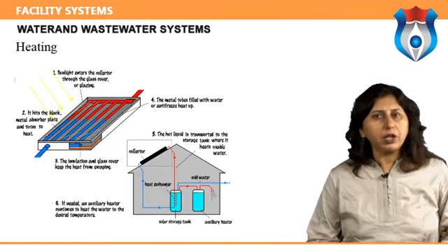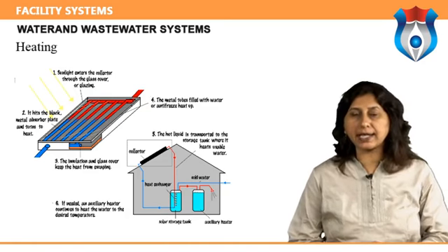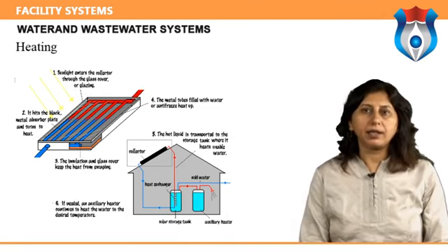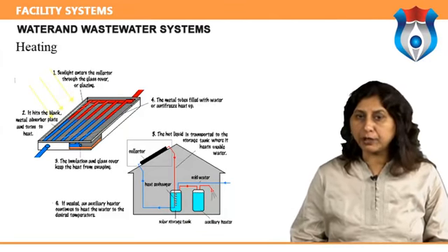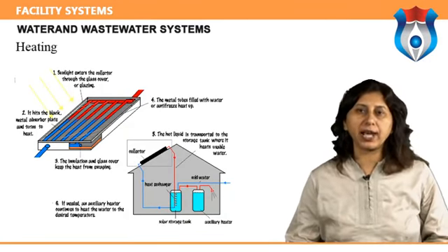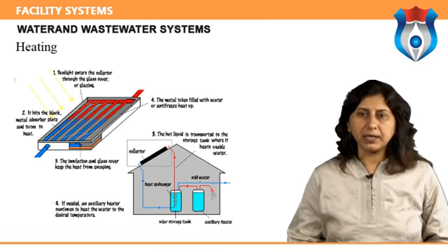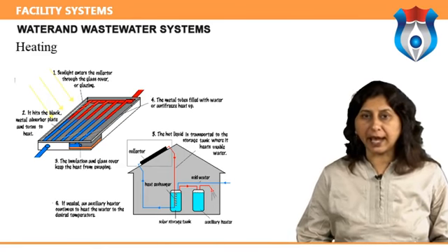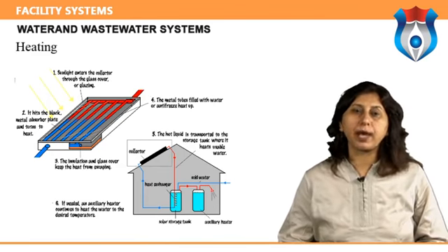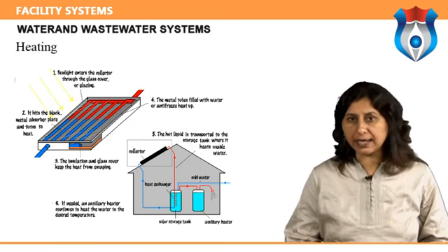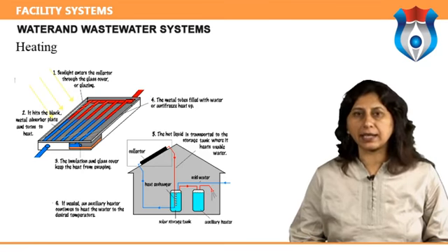Heating. The hot water tends to flow upwards and cold water tends to flow downwards. The elevation of the supply and return lines are therefore important for proper functionality. The low differential pressure in the system demands increased pipes and valves dimensions. The gravity system will also have a relatively low heating capacity because of low medium temperatures in the heating elements.